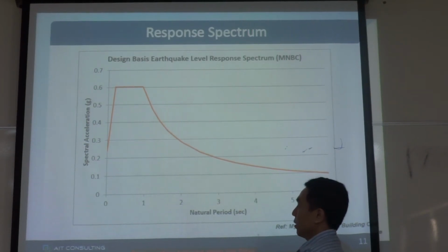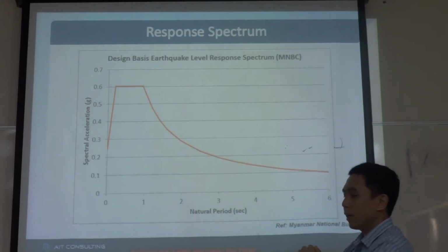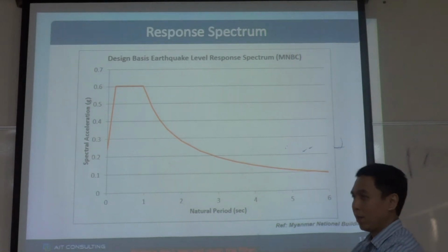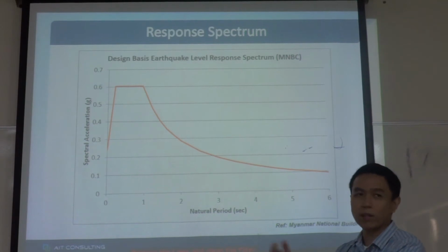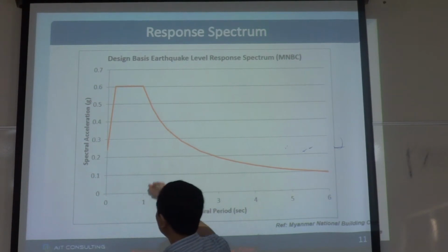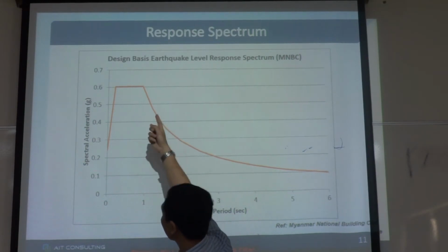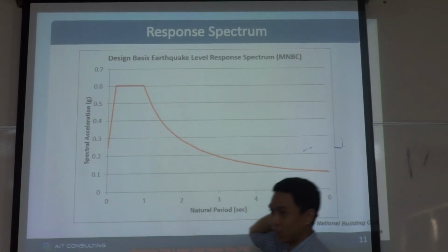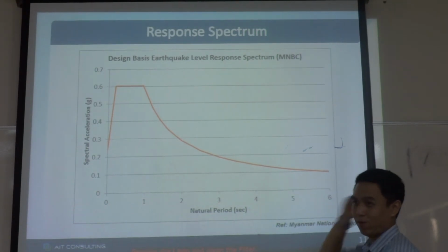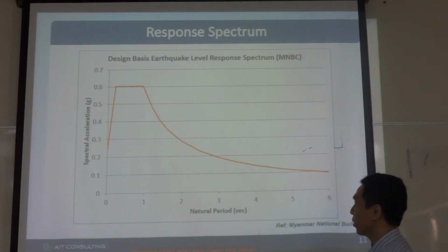So normally when we measure the base shear, we also mention it as a percentage of the weight of the building. The base shear is 5% of the total weight of the building, 10% of the total weight of the building, like that. So if your building completely remains elastic for a 10-story building, the spectral acceleration is 0.6 g, so the base shear will be 60% of the weight of the building. This is if the building remains elastic, which we reduce by the R factor.